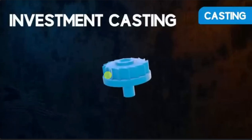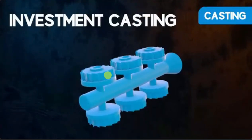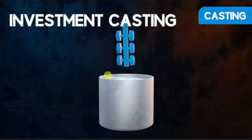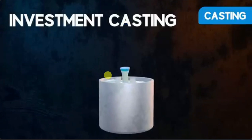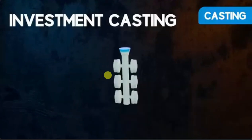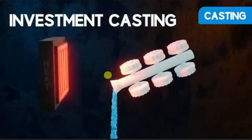The next type of casting is one that is widely used in industry: investment casting. The wax tree is dipped into a slurry to create a ceramic mold. Heat is applied to melt out the wax.